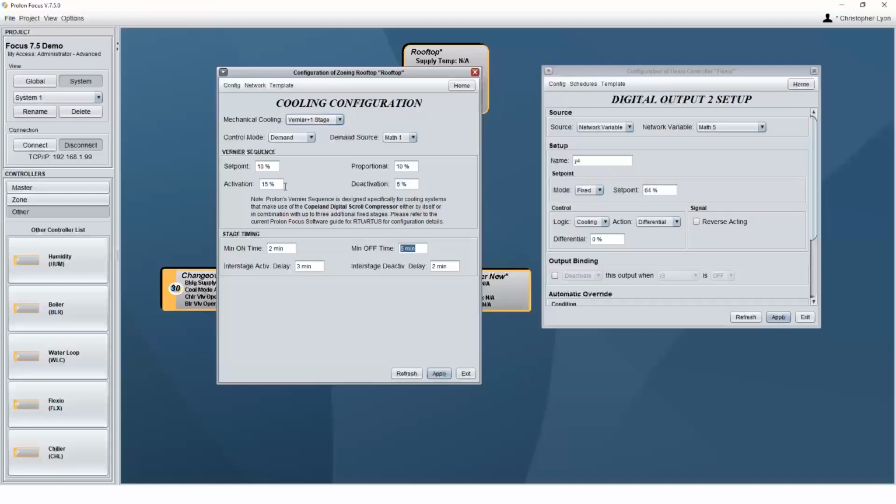Okay, per Copeland, you can run this down to 10%, but at 10% capacity, you end up vaporizing the oil, atomizing it out of the compressor. It gets caught in the evaporator, doesn't make it out of the condenser, whatever, because we're running at such low pressures, we don't have the velocity to push that oil back to the compressor, okay?